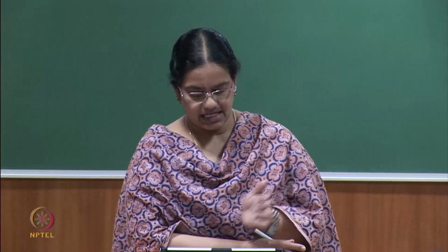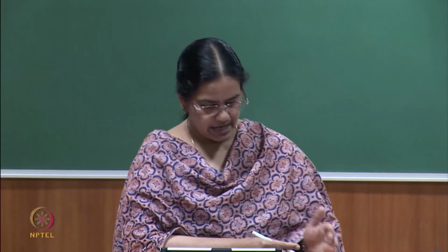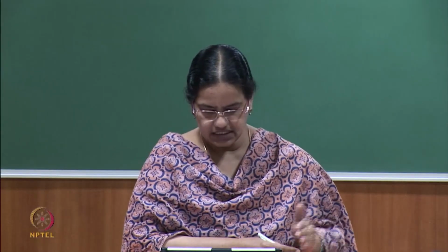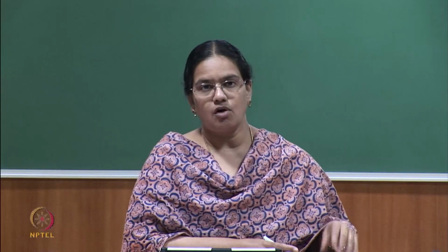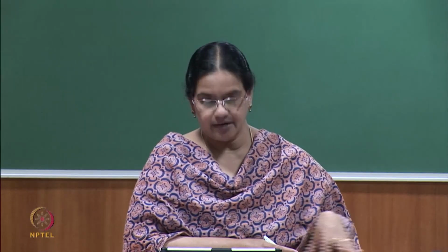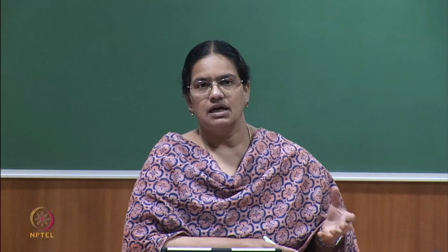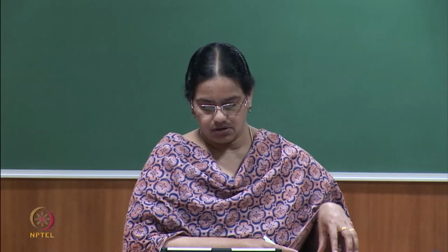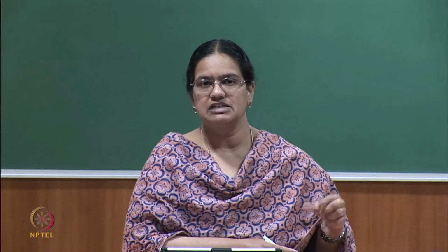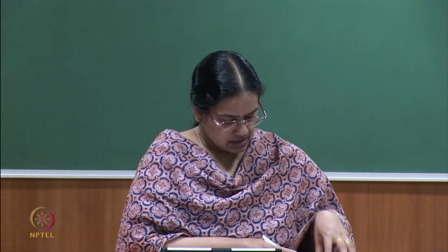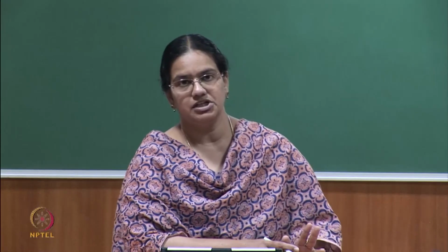So, if I wrap up on the AOA diagram and the AON diagram, AOA diagram came into existence first and then AON came in. Drawbacks in the AOA I have covered then and there, primarily the dummies and also sometimes misguidance with the slack values, because we are calculating it on events. Okay. In AOA we have forward pass and backward pass, primarily with the early event time, late event time and the slack calculations.